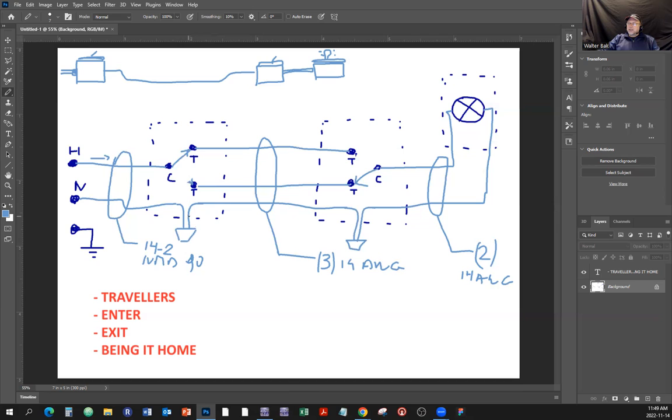It's because the stages of the construction site or installation will be first, you'll be assembling the raceway. So you'll be running the conduits, mounting the device boxes, running the pipes between them, and assembling all the raceway that we need to assemble before we pull the wires in. Later, the next stage would be pulling the wires. Now, assembling the raceway can last a few days. It can last a month. It can last 2 months, depending on the size of the project you're doing.